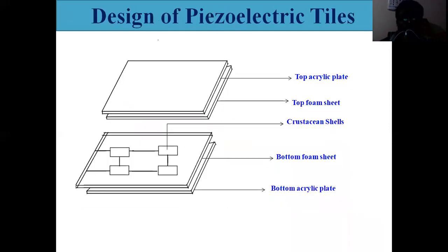Okay, this is the design of the piezoelectric tiles. Here we have the bottom acrylic plate, and after that a foam sheet. After that are the piezoelectric devices, which we have connected in series or parallel according to the requirement. Then the upper portion is also given a foam sheet, and the final layer is an acrylic plate. This is the full design of the piezoelectric tiles for this device.